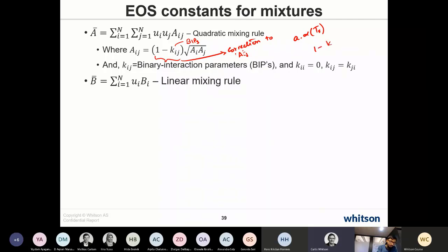They just had a correction term Lij. And Lij, basically, they found if it was slightly less than 1 or slightly greater than 1, would vastly improve the vapor-liquid equilibrium calculations of some binary systems in special cases. So an Lij of 0.98 could have a big improvement on how accurately it was predicting different behavior.